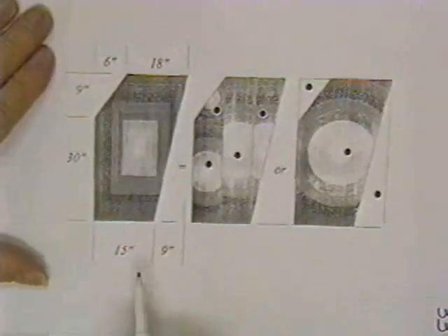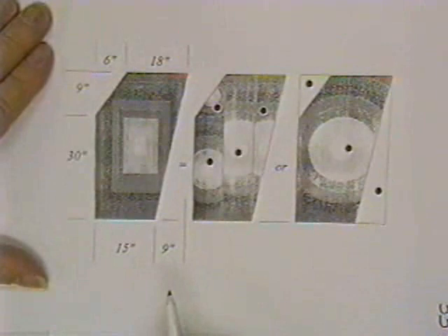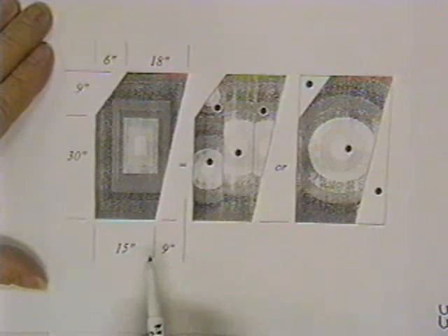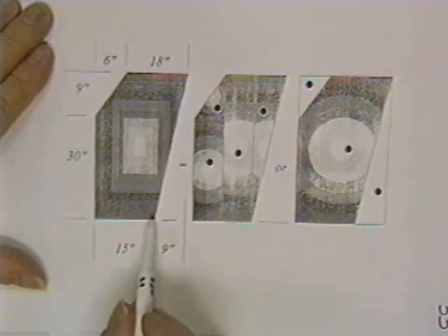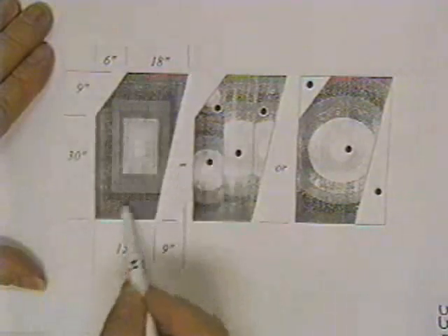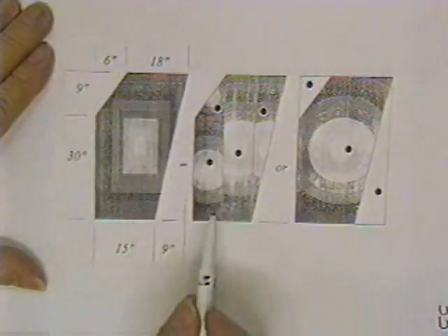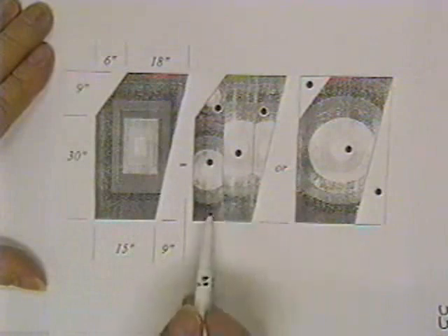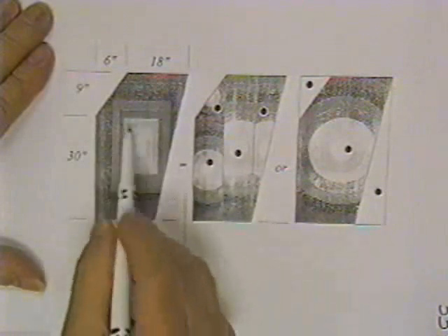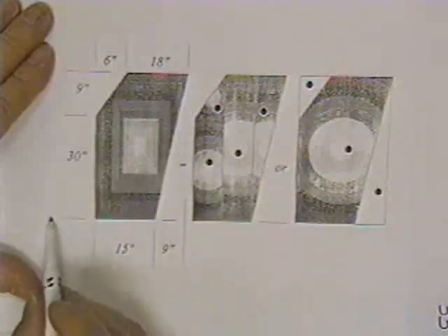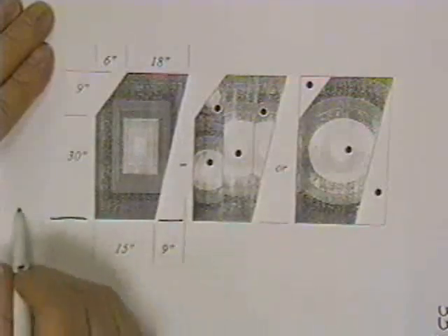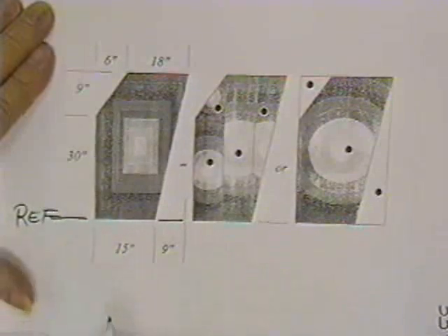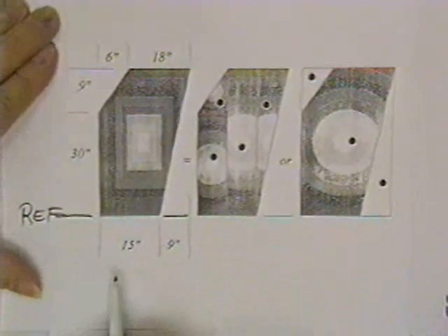Alright, sometimes I'll give you something that looks a little strange, and ask you where the centroid is, or what the moment of inertia is. It works just like all the rest. This doesn't look too good. This is supposed to be just one solid piece, and the computer didn't render this shading very well. You solve it like always. You draw a reference axis at the base, and you discuss only areas that you fully understand.